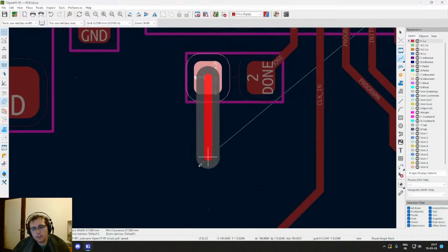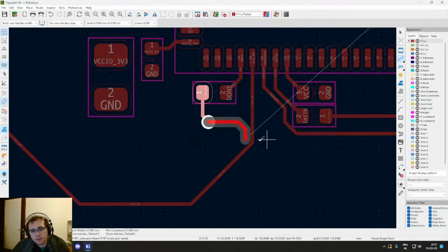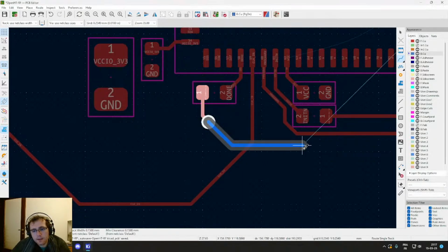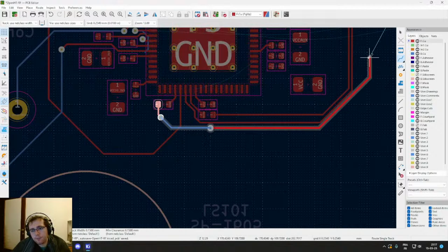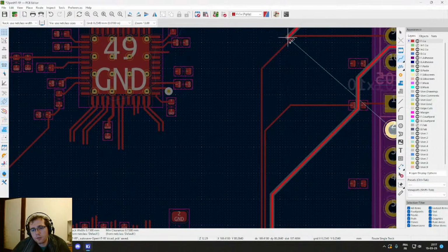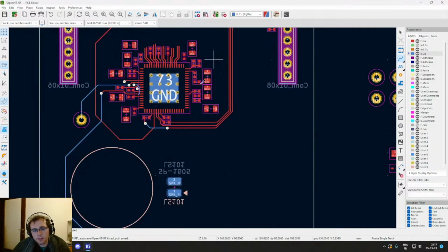So this done signal is not gonna be used much. So init and programming and done are used for the programming of the FPGA. So it's gonna wiggle a bit at the beginning and then not much. So we should be good. This needs to go to the bottom, and as long as we don't need any crossing, let's use the top layer, sorry, and like this.